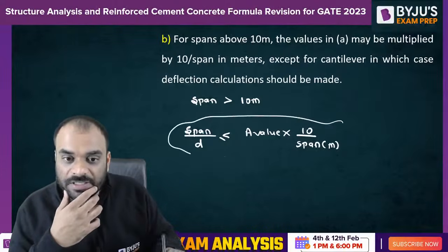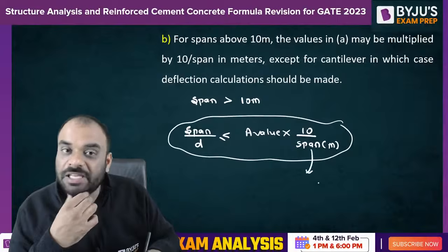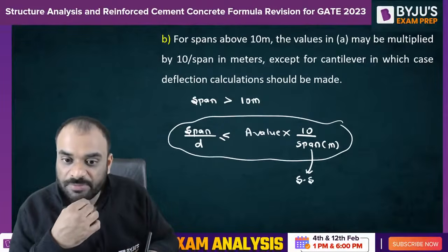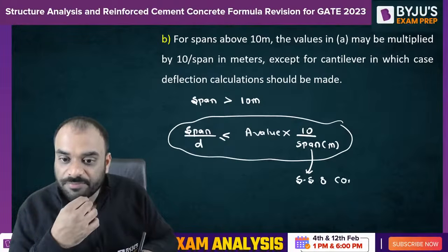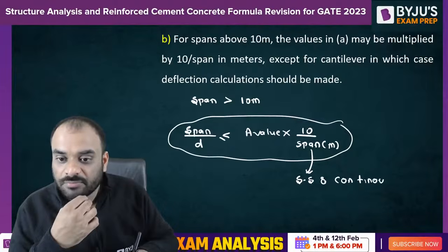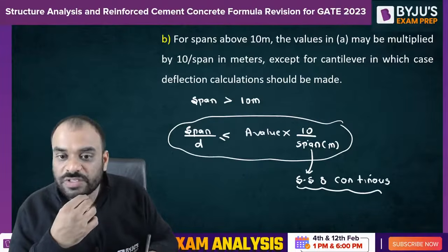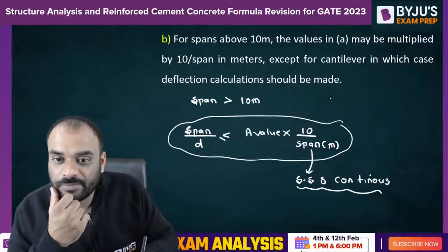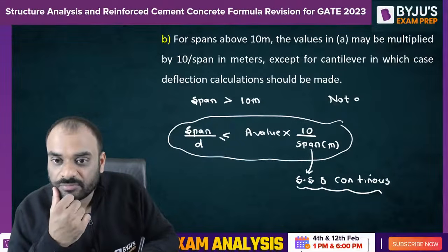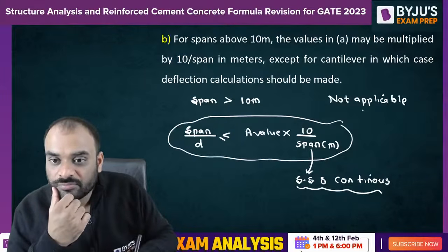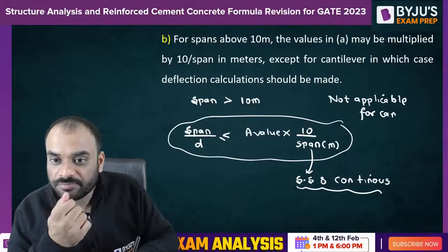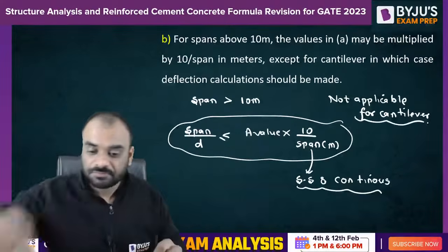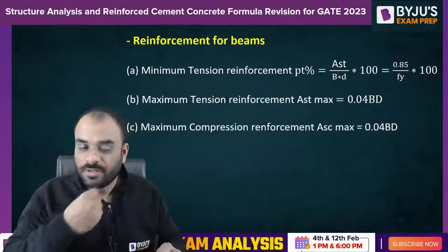Clear? But this particular factor is only applicable in case of simply supported beam and continuous beam. Please do not use such formula or such modification in case of cantilever beam. Not applicable for cantilever. For cantilever, it is not applied. Clear? Okay. Next,